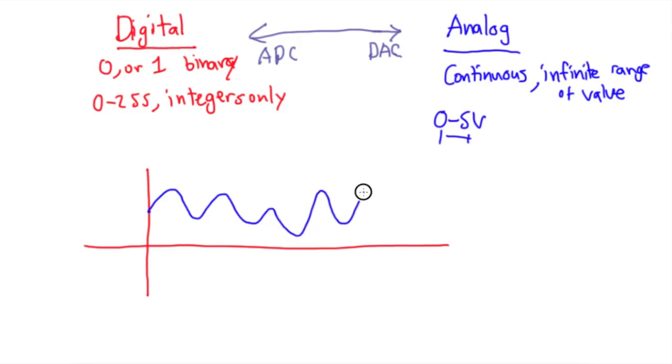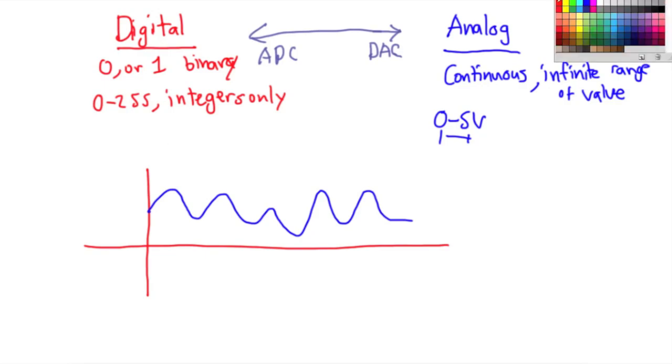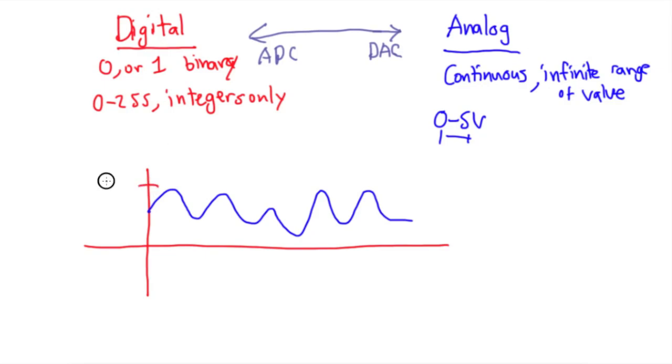And again, the issue is that it's going to range at most from 0 to 3.3 volts, because that's the microcontroller's logic levels. So you can only go within that range. 3.3 volts is the maximum, and this is 0 volts right here at the bottom. What it's going to do is create some arbitrary voltage, and then there's going to be some time lag between the time it takes to convert to the next voltage. Once it gets to the next voltage, it's going to convert to the next one, and then the next one. Effectively, it's going to become a series of little jagged rectangles.